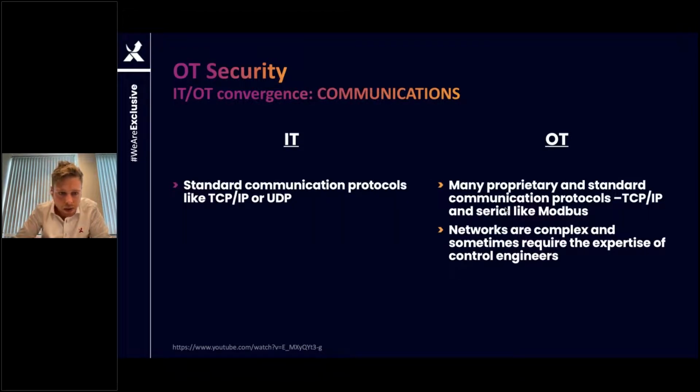Communications. IT uses standard TCP, UDP. OT also uses serial Modbus. We have also indicated TCP/IP because a lot of systems are now making the step to the TCP/IP stack with the convergence of OT and IT, but a lot of them are still using proprietary protocols. And these OT networks are often complex, ring topologies and whatever topologies, so they often require the expertise of control engineers.